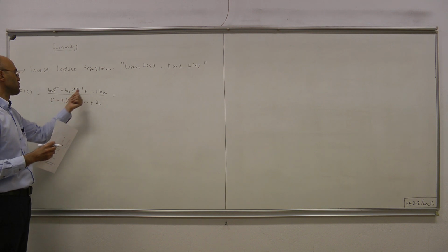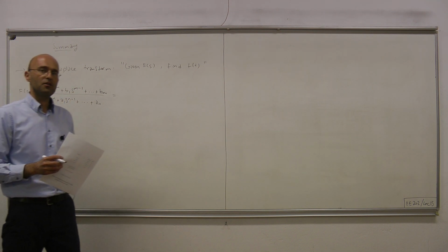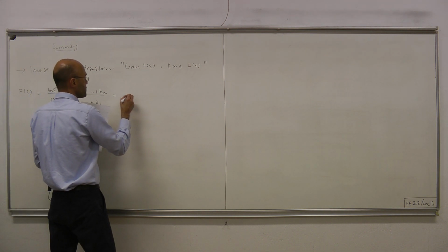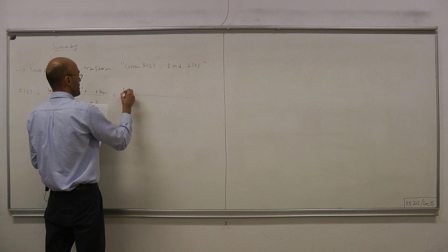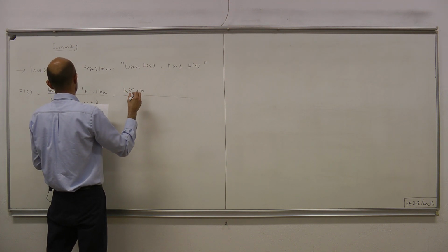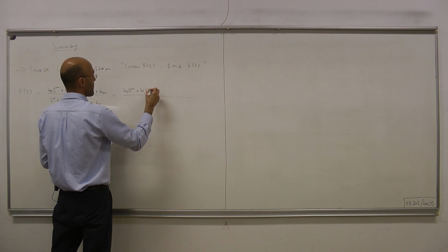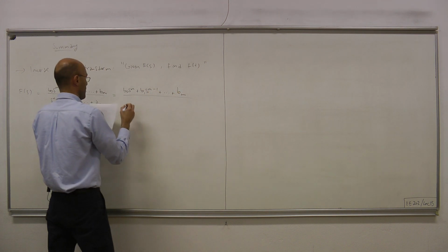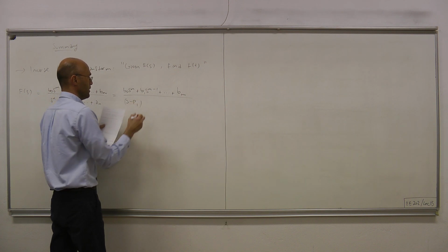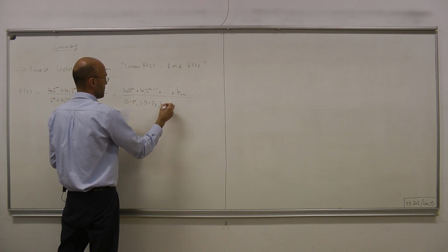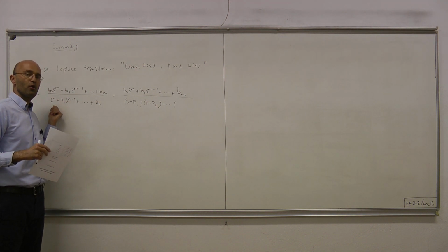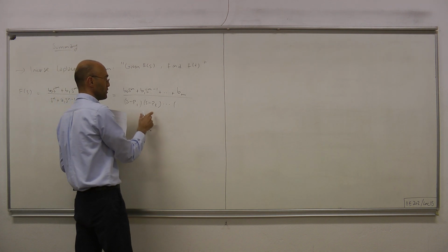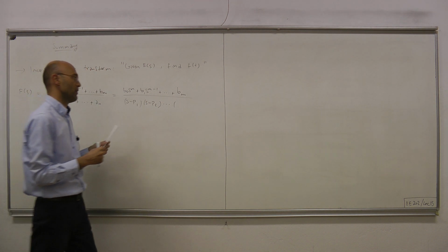We call them poles. The roots of the numerator polynomial are called the zeros of this transform F(s). So suppose that the denominator can be written as (s - p1)(s - p2), okay? Since this is a polynomial of order n, we have n poles. So that means we're talking about n first order terms multiplying each other.